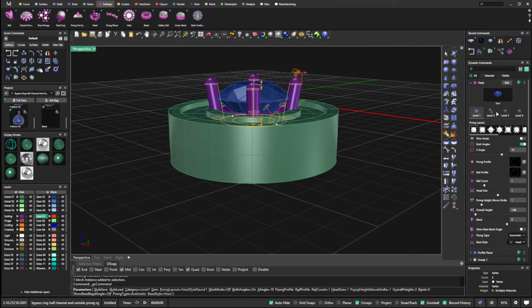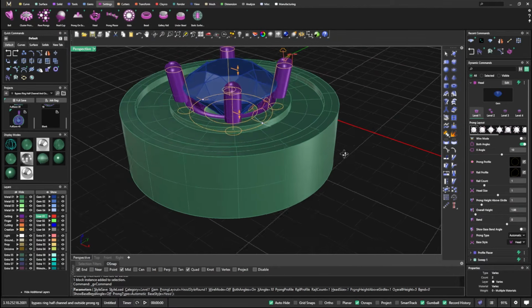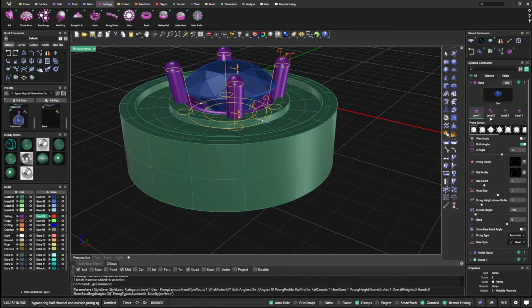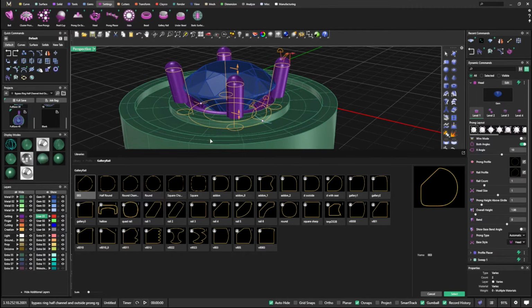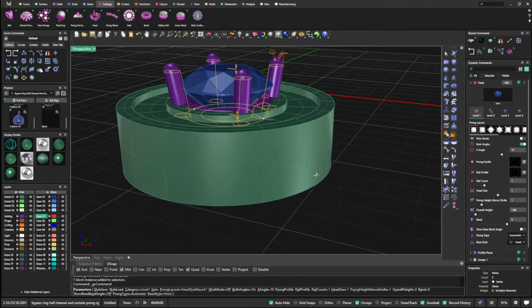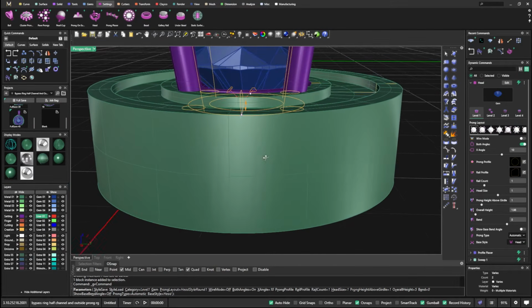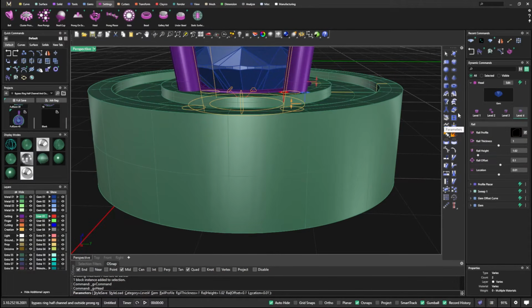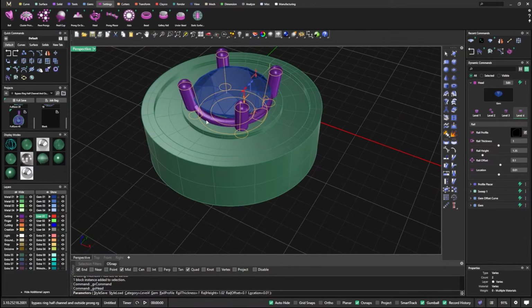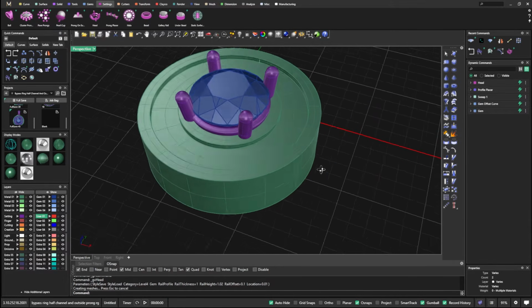And if you need to know any more about all these commands with each individual level of the head builder, we have previous videos in this series that talk about all those, so go back and check those out. So right now I just have one rail out there. Let's go to that rail profile right here. I'm going to change that up just a little, something like this here. And we'll just go ahead and take that. Maybe I want to make it a little thicker, so I'll go to the rail itself, level 4, and we'll just bump that up just a little bit, something like that, right? So it's a little bit above our inside base there, and then we'll take it, right?